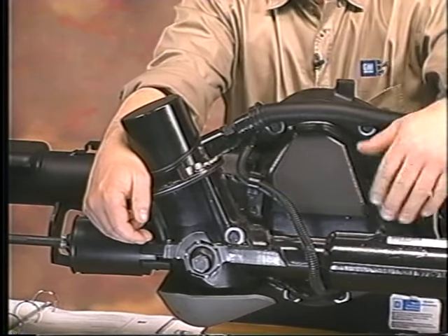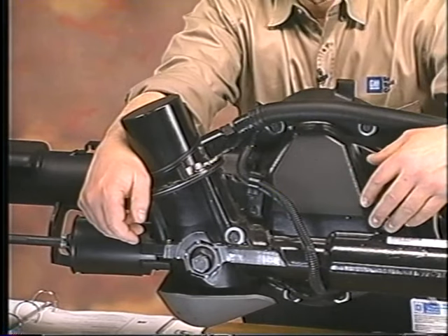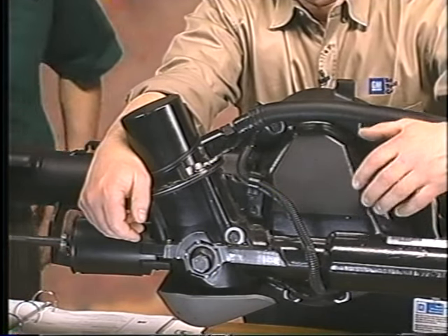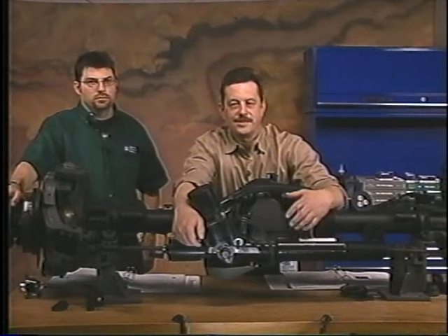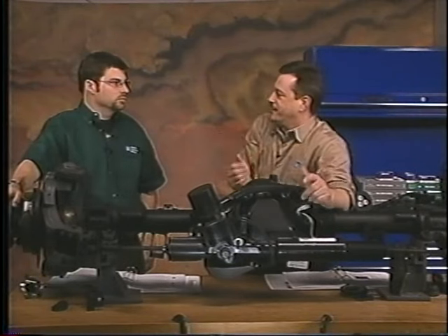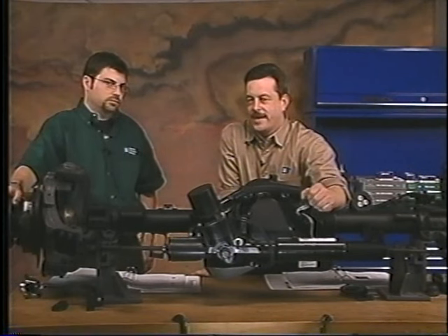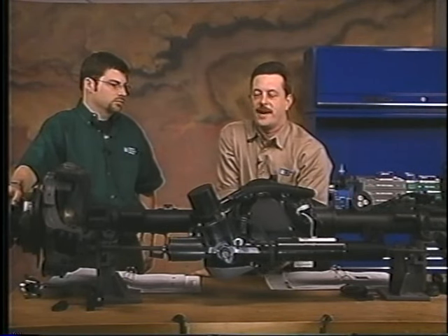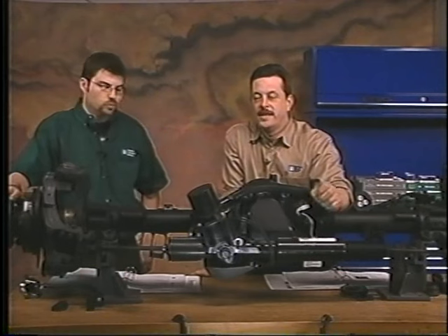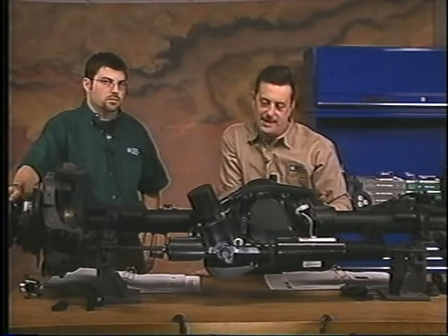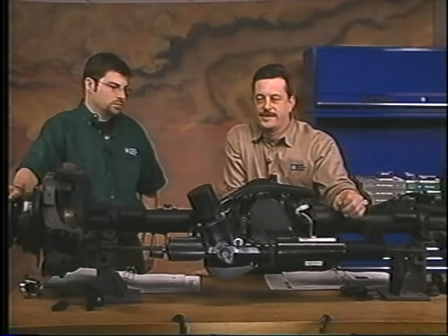Now, quickly about the axle itself. It's a Dana 9 3/4-inch axle, pretty heavy duty. It uses a synthetic fluid. Okay? Synthetic fluid. Now, with that fluid, there's no change interval. Don't need it. Okay? No change interval. But if you had to drain fluid out of this thing, they do give us a drain plug down at the bottom. You're going to have to pull the shield off if it has one, and then pull that plug out and drain it out. Of course, we've got a typical fill plug on the side where it's spec.